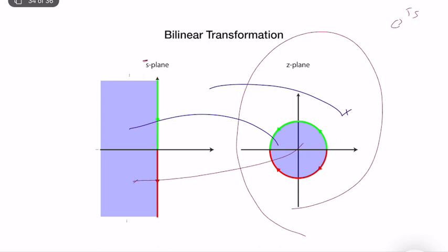The good thing is, this implies that if I have a Z-domain transfer function, I can map my system to the S-bar domain using the bilinear transformation, apply Routh-Hurwitz or similar methods, check the stability, and it will guarantee the stability of the discrete-time system. So in that respect, the value of T is just the user's choice. It's not important. Just choose any T, and it will give the same result in terms of the absolute stability metric.